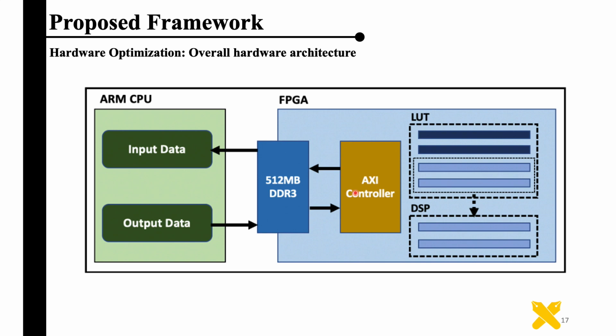During the implementation, we encountered the problem of LUT shortage. As a strategy, we move part of the LUT calculation from LUT to DSP, returning the binarized data to 16-bit floating point, instead of the original 32-bit ones, so that the model can be embedded into PYNQ-Z1 successfully.